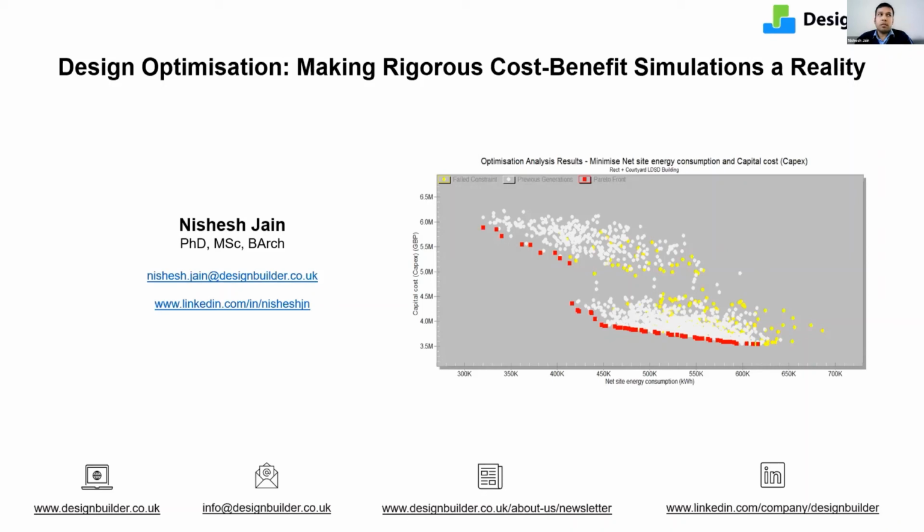So you define cost tariff information, and because you can also do life cycle cost as an option, you can also define for how long you want to do these costs, and what the change of these costs is. These are reasonably easy fields in DesignBuilder to set up. There's an economics tab in DesignBuilder where you put in all these cost tariff information and life cycle related things.